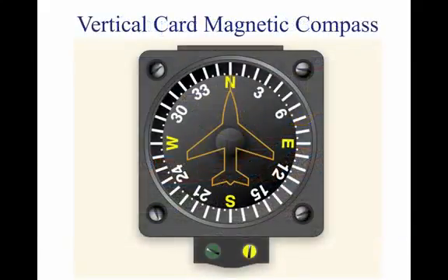The floating magnet type of compass not only has all the errors just described, but also lends itself to confused reading. It is easy to begin a turn in the wrong direction because its card appears backward. East is on what the pilot would expect to be the west side.